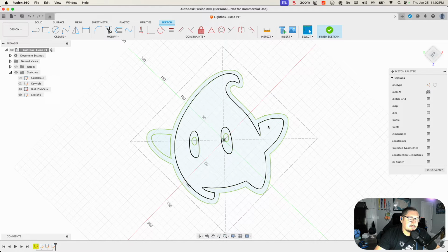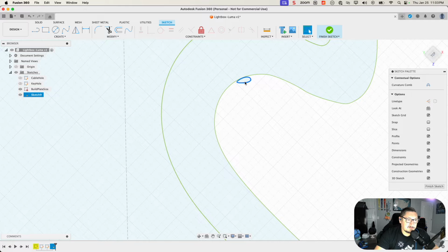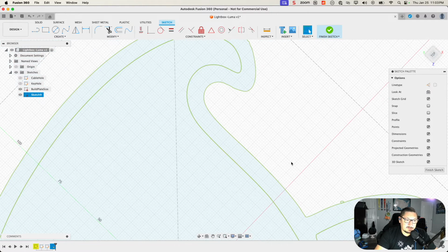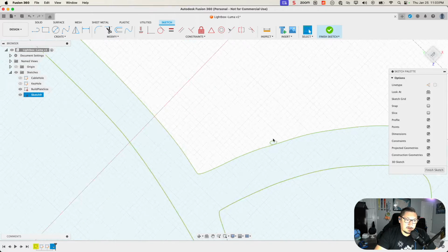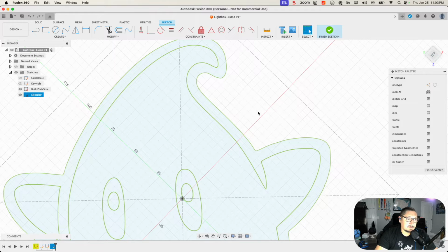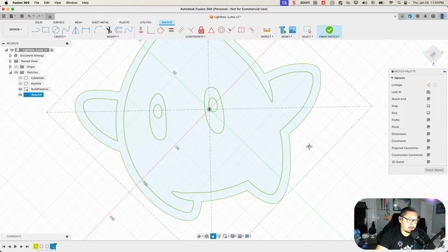So now that we have this, I want to go through and give the model a once over because I didn't build it, I just converted it. There might be some remnants of some weird conversion artifacts. So I can already see a couple, and it's hard to see unless we zoom really close in. There's these little circles that it picked up, which we'll just double click on them, delete them, and look through the model. Delete that. I don't see much else in here. Everything else looks pretty good.